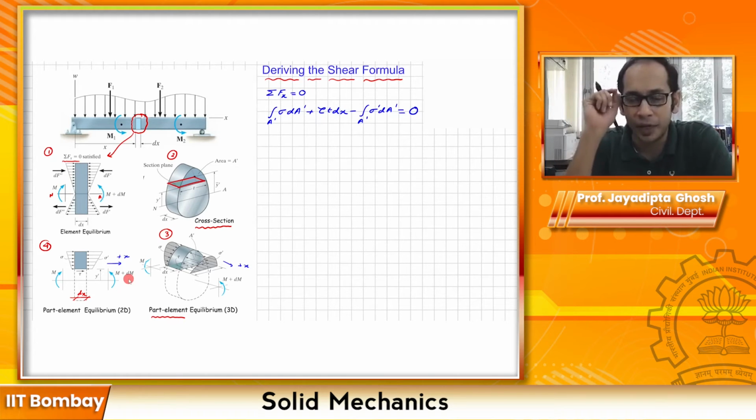One very important thing is that this shear actually exists only because the moment at the two faces is different. Remember when we talked about pure bending, where both the faces were M and M. What was pure bending? The case where shear is 0. If you have M and M both the same, instead of M plus dM it is just M, your tau essentially vanishes. So for pure bending you did not have shear, but when the bending moments are different at either face, only then are you going to have shear. So this shear is actually induced by the moment that you have in your structure.